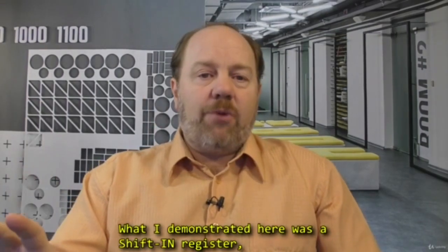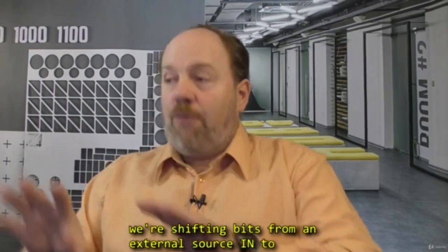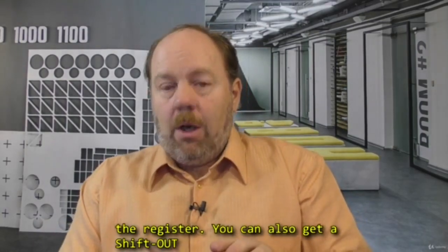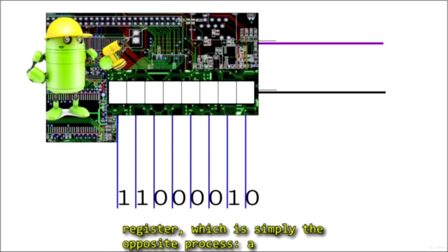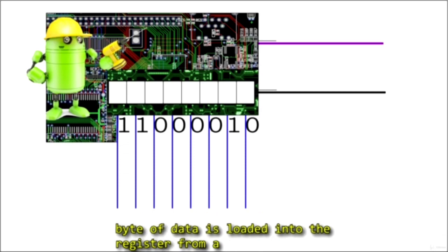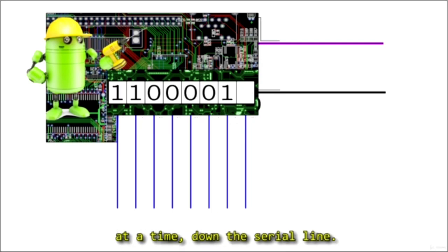Now, what I demonstrated here was a shift-in register. We're shifting bits from an external source into the register. You can also get a shift-out register, which is simply the opposite process. A byte of data is loaded into the register from a parallel bus and then shifts the data out one bit at a time down the serial line.